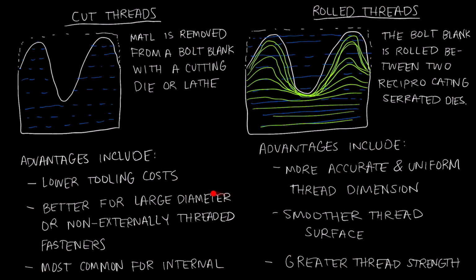Then we have that it's better for large diameter or non-externally threaded fasteners. And lastly, it's most common for internal threads. So for nuts, you will almost always have cut threads on those parts.